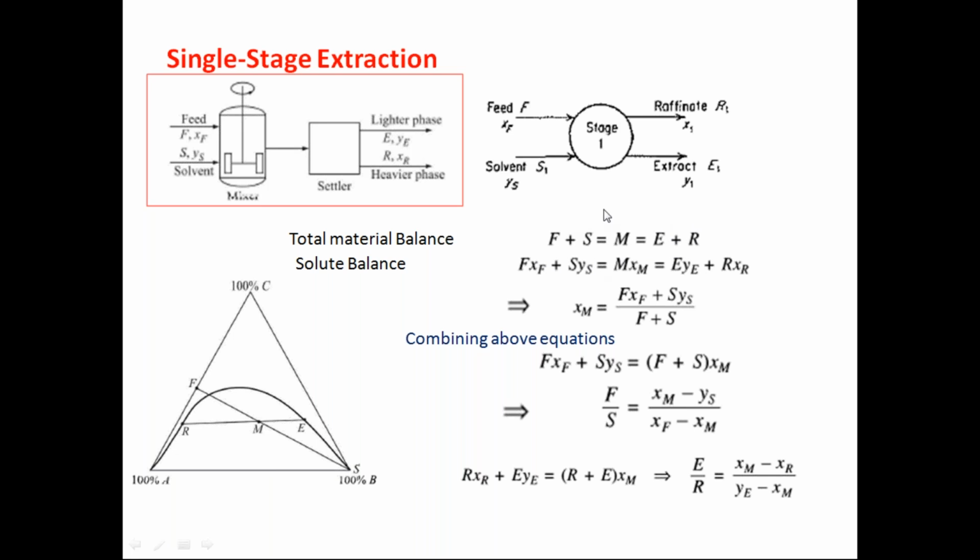So this is how you will get the total material balance equation. Then the solute balance equation. What is a solute? Solute is one of the components in the feed, and the feed will be dissolving into the solvent, and it will be there in the extract phase as well as the raffinate phase. The solvent may have C or may not have solute.